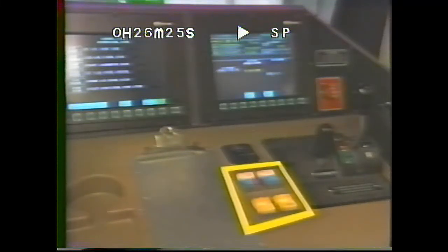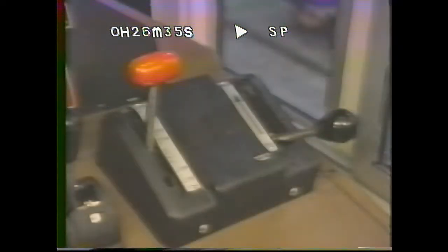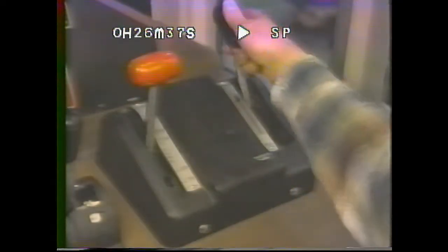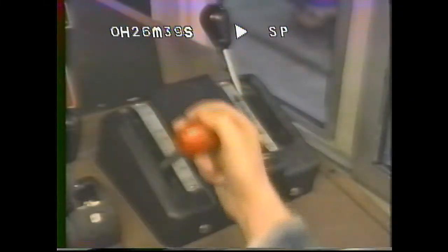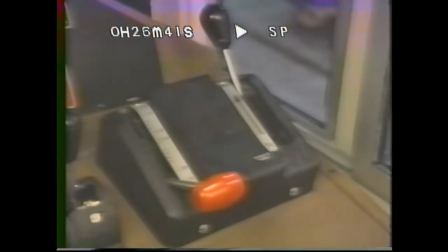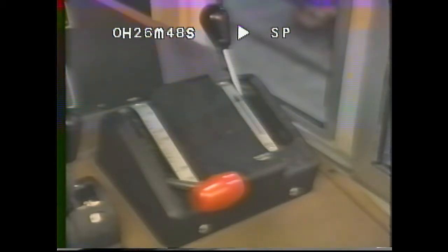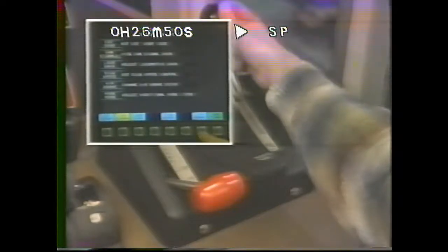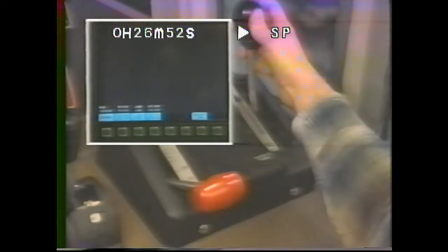The horn, bell, and sand switches are located in the center area of the control stand, to the left of the reverser throttle dynamic brake controller. On the right-hand side of the control stand is the air brake controller for the EPIC 3102 brake equipment. This equipment is identical to the EPIC equipment found on our SD-80s, and its setup, cut in, cut out, and operations procedures are also the same.